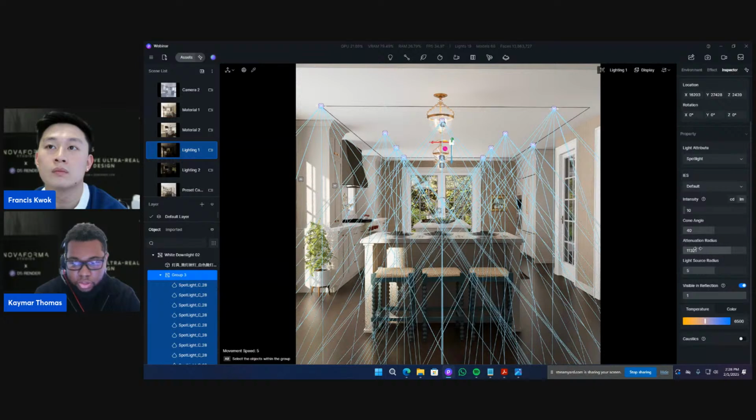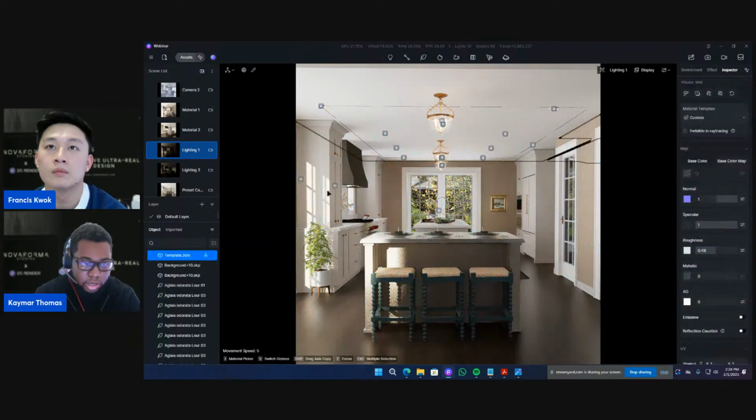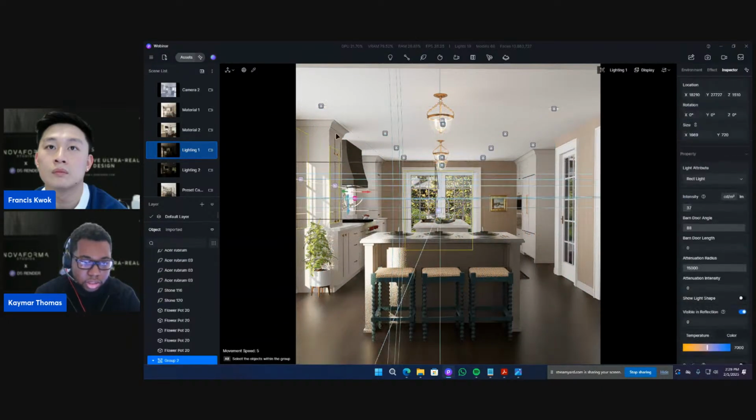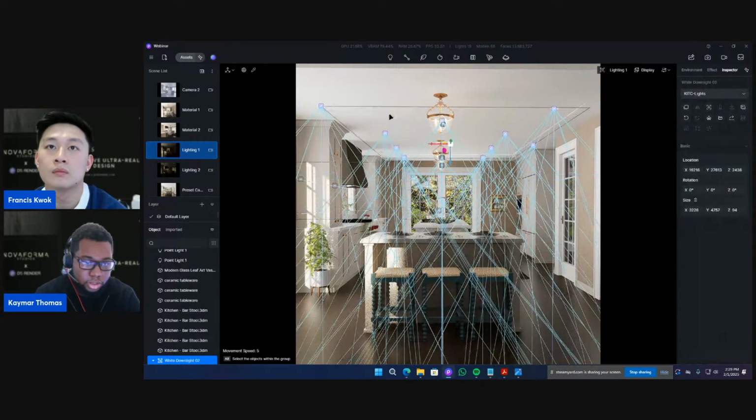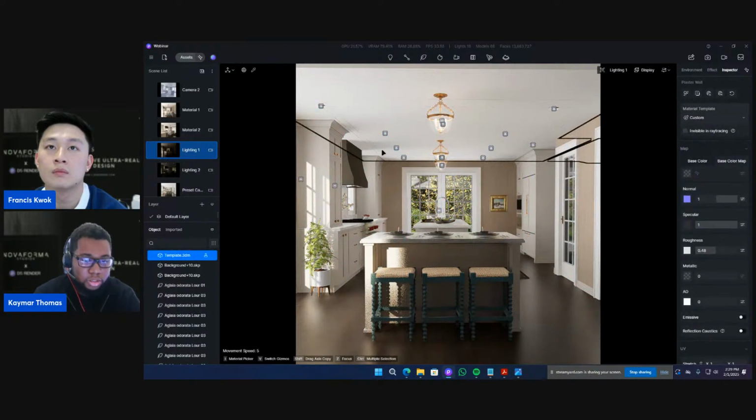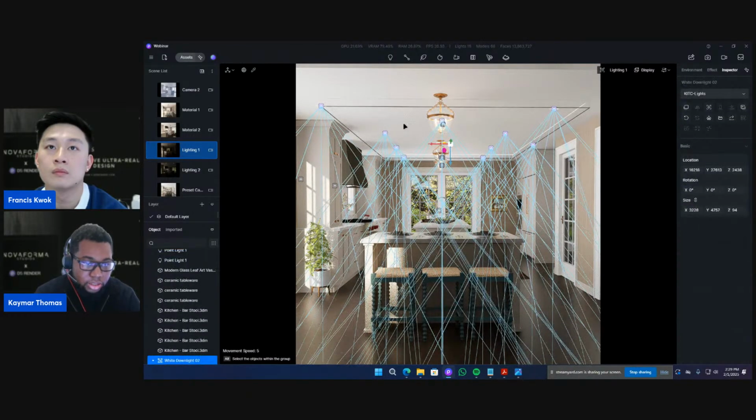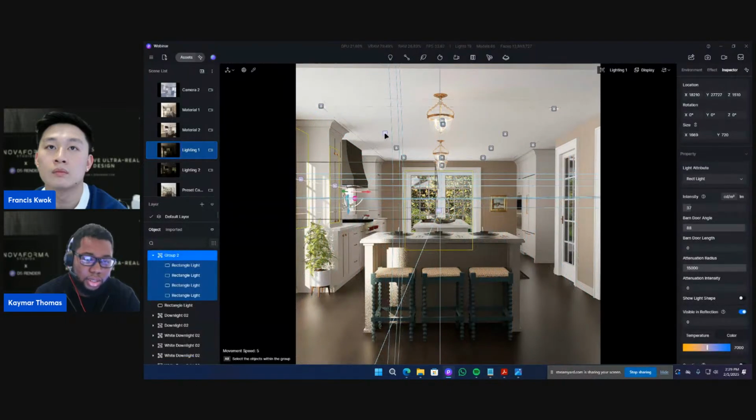And for this, you can max out the radius as well because you just want to get the overall light in the space. So we have our 37% here for intensity for each one, and then we have the 10% up here. And these could differ. Now, if you were to do the opposite and made the interior lights higher than the outside lights, you start to get a nighttime scene. And this is how you can achieve different types of rendering scenes, mimicking certain times of the day.